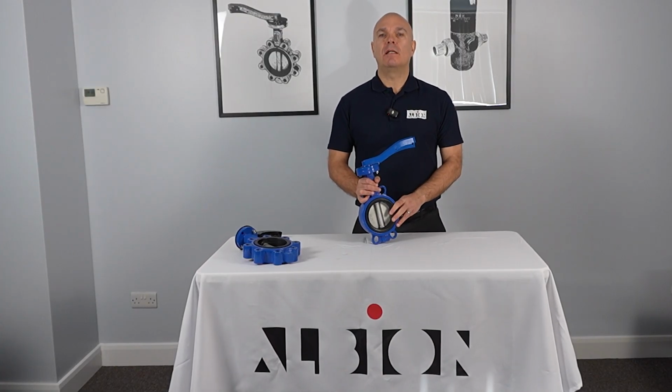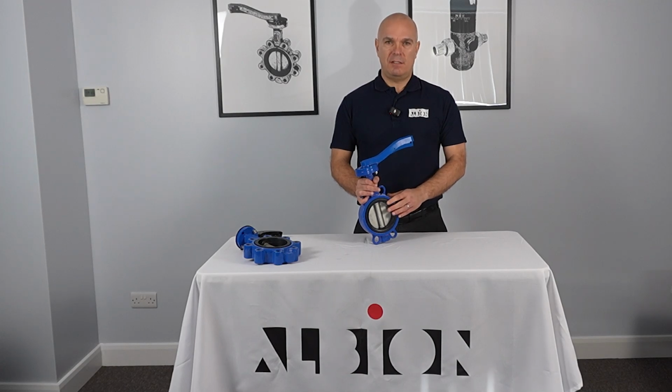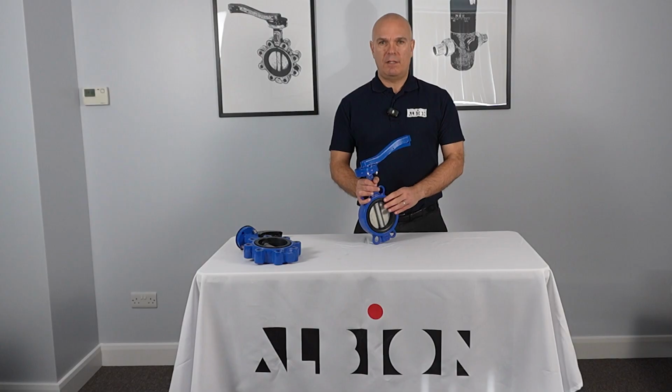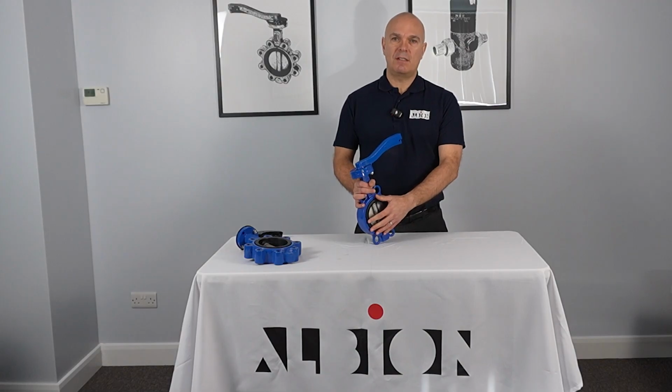A wafer pattern valve is a type of valve designed to be mounted between two pipeline flanges, secured by a series of bolts that pass through both of these flanges. This type of valve would connect to flanges either side of the valve by using a threaded bolt, whilst utilising nuts and washers for securement and leak prevention by compressing the protruding sealing face on the valve with the mating flange.